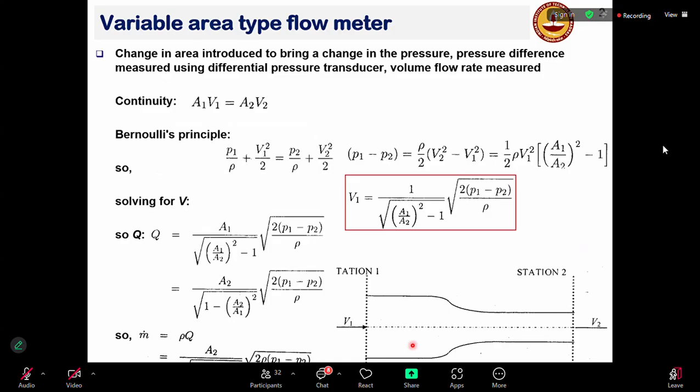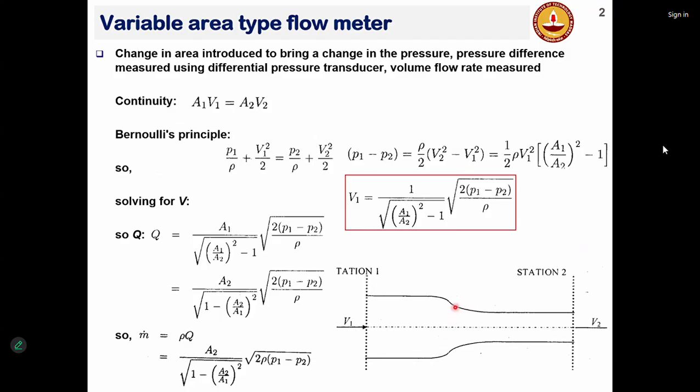Because of this, if my understanding is right, if V1 is very high, then the eddy flow loss will be very high in this bend area. Yeah, you will typically have these eddies, these recirculation zones, somewhere here. So wouldn't it be a better design if you just make a taper, a straight face coming down to V2 in that way?